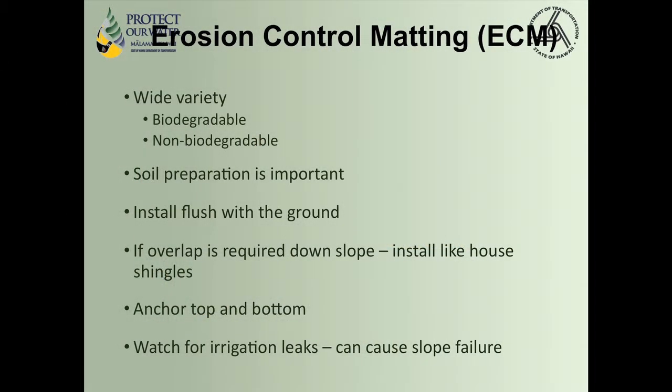Erosion control matting. There is a wide variety out there. There's biodegradable. There is non-biodegradable. Going to talk a little bit about soil preparation is important. And when I say soil preparation, that's more in terms of the construction requirements than BMP, but it enters into it. You have to have complete contact with the ground.